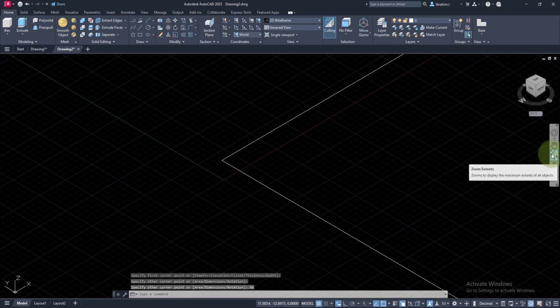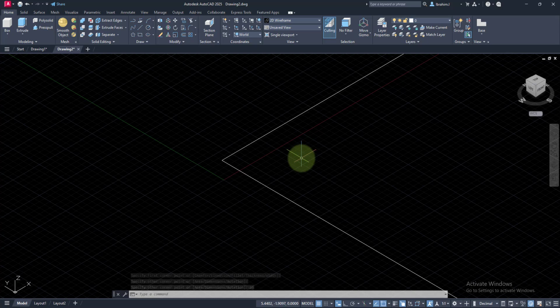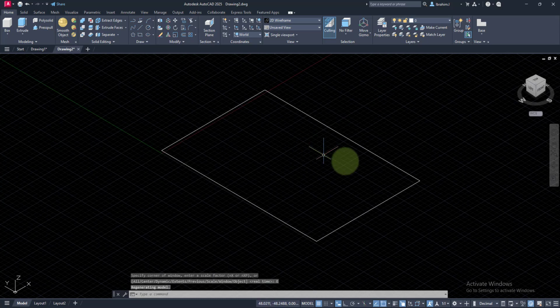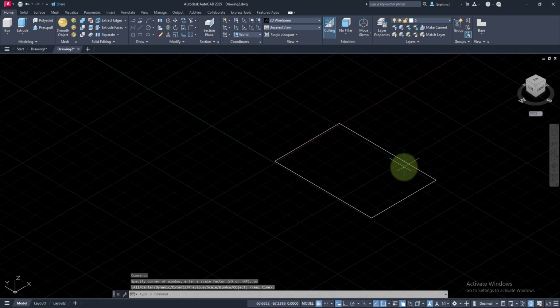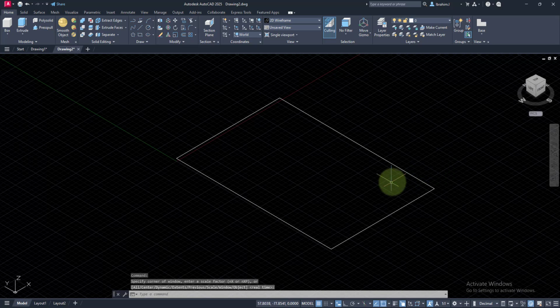When you click on zoom extend, again, if you want to use your shortcut very quickly, you press Z, enter, E, enter, right? It zooms and brings everything in place. That is the conjunction of Z, zoom, extend, right? It shows everything that you have on your workspace, and this is exactly the slab that I'm talking about. Again, from a sketch, you can get your 3D model. How do I get my 3D model from a sketch?